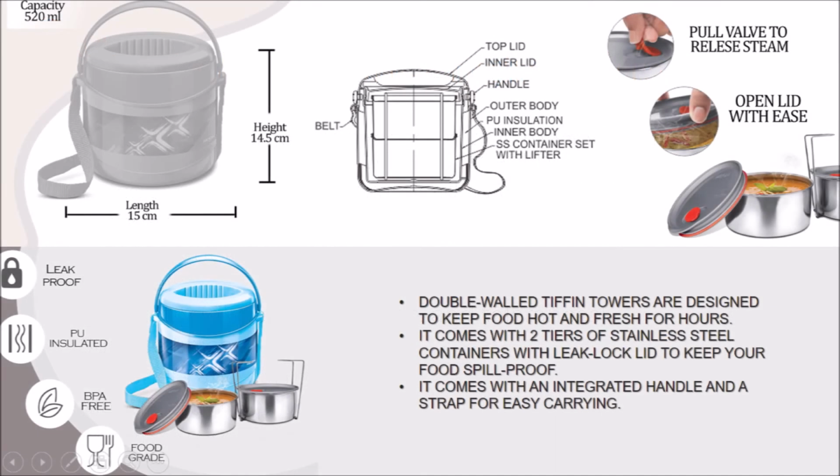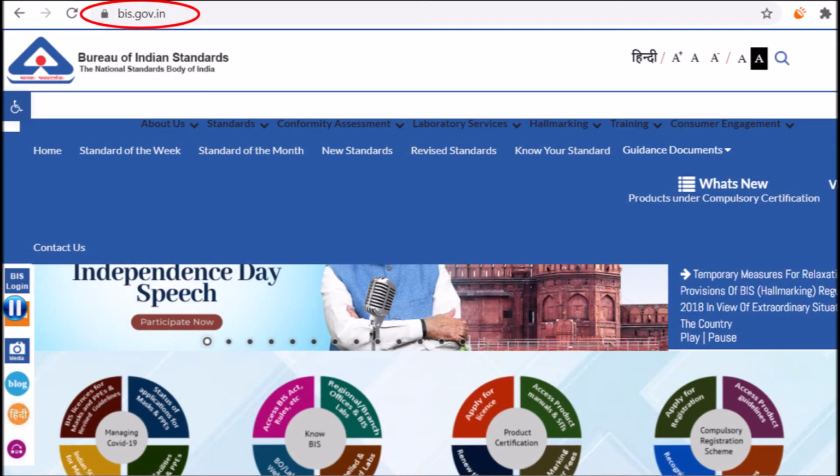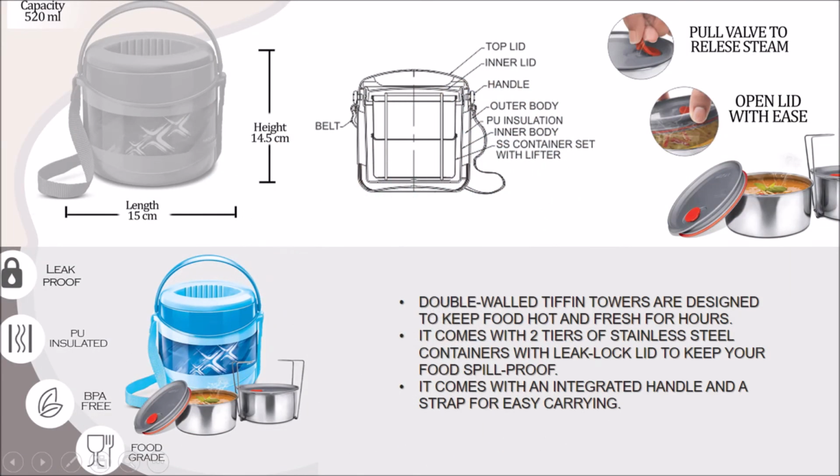Let us continue with the lunchbox design. Suppose you have selected the metal box with rubber lids and plastic outer cover with a plastic handle. You can go to the Bureau of Indian Standards website and download the various Indian standards for utensils and cookware. Component interface here would mean how the lids and the boxes will be attached to each other, the fits and tolerances. If you are using stainless steel, it has certain specifications for the surface finish for food grade utensils.